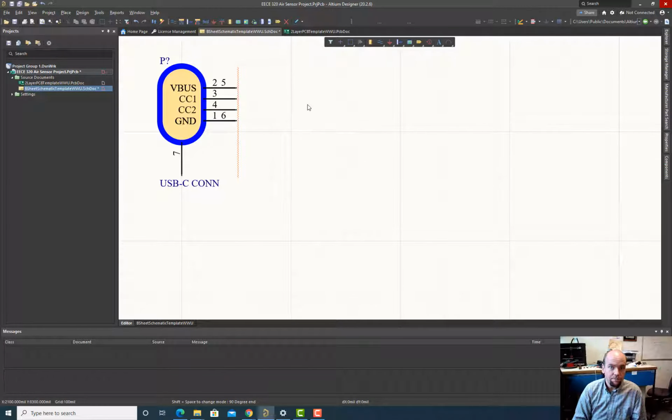And actually, with USB-C there are extra features you can use to allow really fancy power connections. There are ways for a device to communicate with a host to say, you can give me 15 volts, and I can take 15 volts. I don't know what the highest is, maybe 24 volts, 4 amps. I can't remember the exact thing, but basically it's possible to send higher voltages over the USB bus. That's something you really got to be careful with. So there's definitely a careful handshaking before that happens.